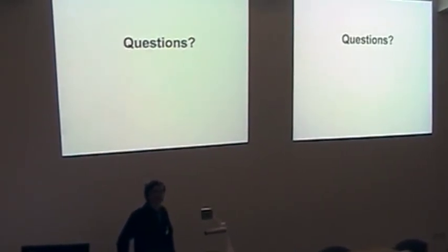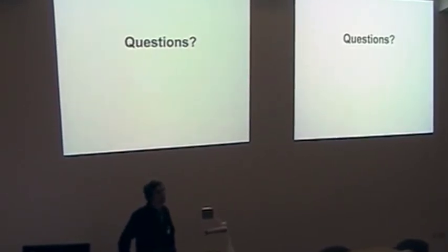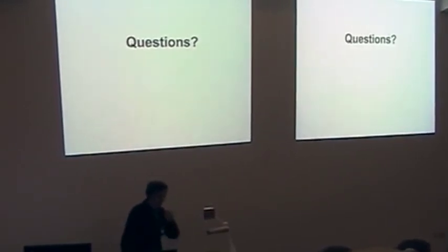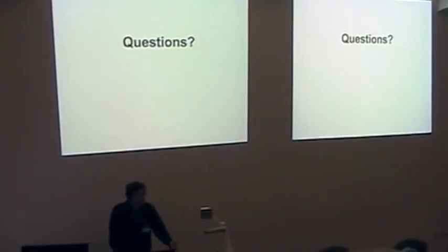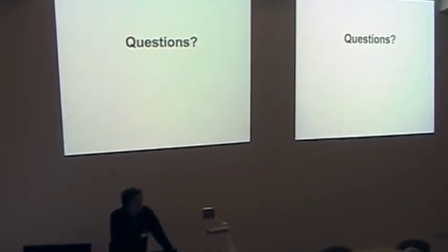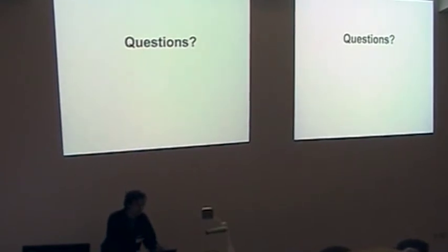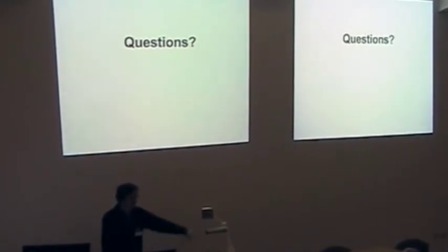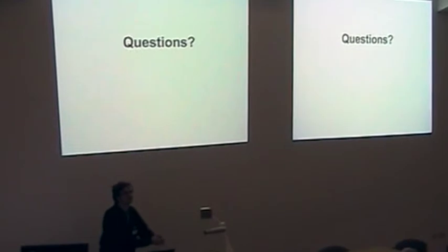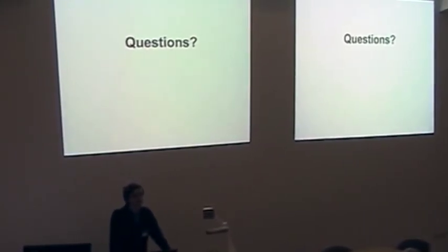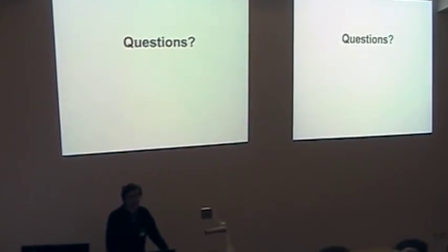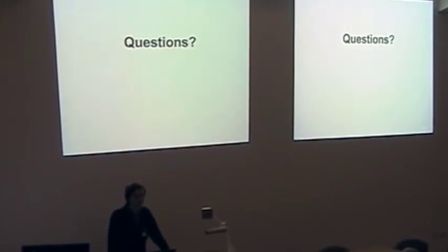Does the binary mode support the macro so you can do I2C sniffing? No. It's got certain sniffing things. But in text mode, they basically built a basic scripting engine, so you can send an entire script and have the thing do stuff. But in binary mode, there's nothing like that. It's very raw right now. Sniffing mode is really, really useful. I have a proper Saleae clone, which is much nicer for doing all of that sniffing. So I don't use the Bus Pirate for sniffing. I have the real thing.